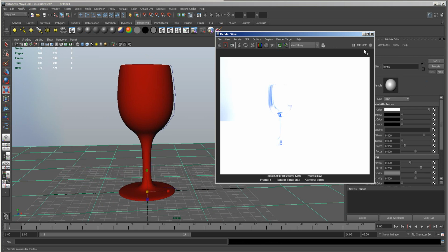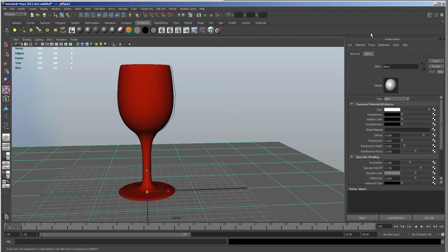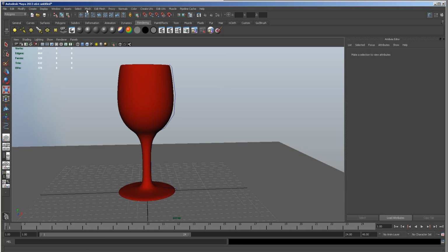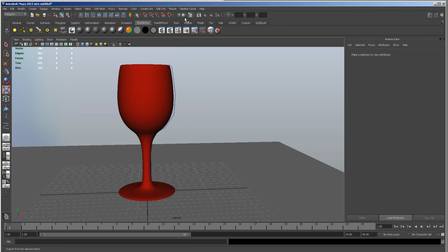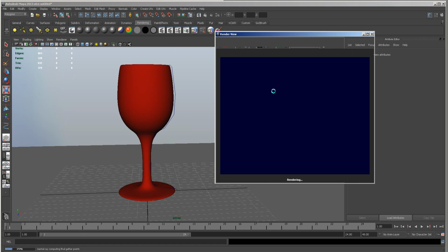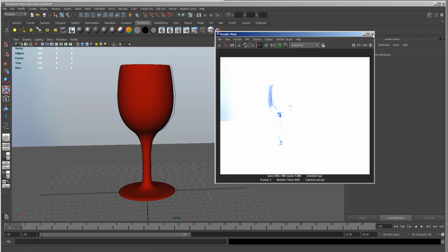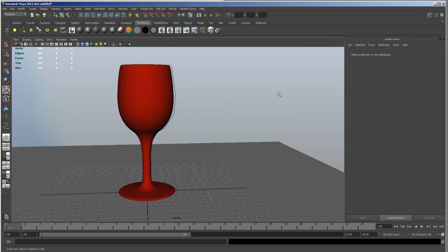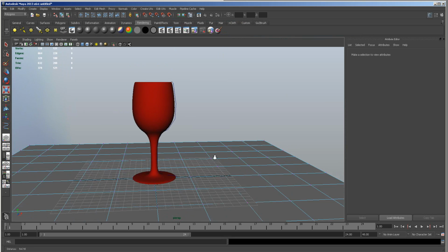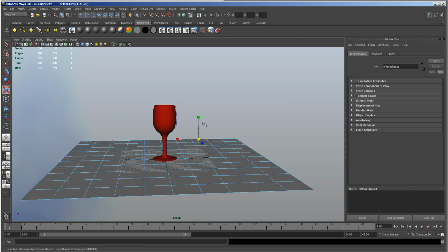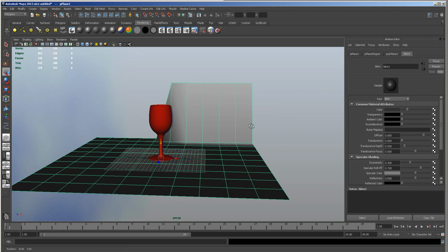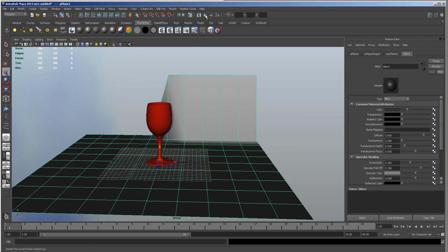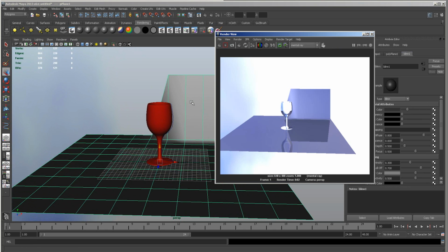Of course it's a bit dark, it's a bit light, so I probably need to come in and change my settings. So let's just turn the global illumination off. Yeah, it's a little bit more, but still a bit burnt out. Probably need to put something in the background. So if I just grab these vertices and just do this, I'll change this to a kind of darker colour. This is just to show you. There you go.